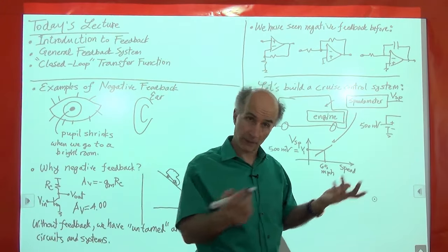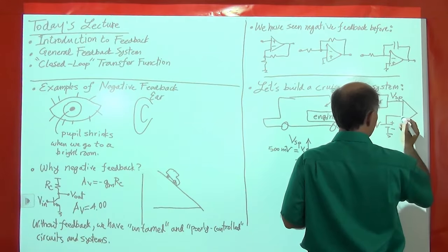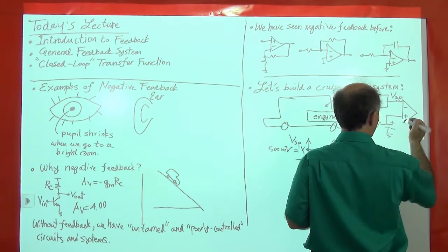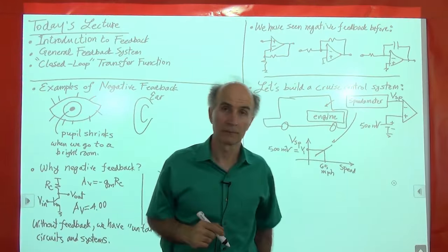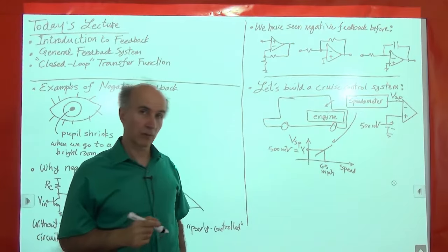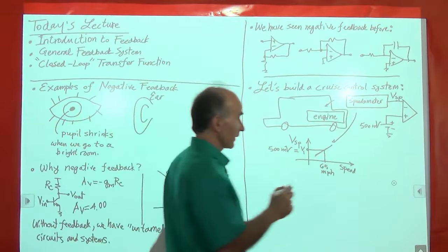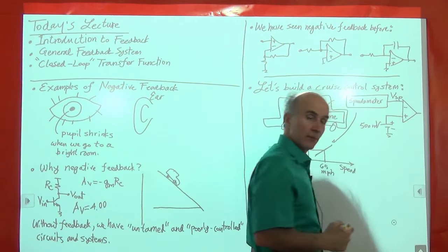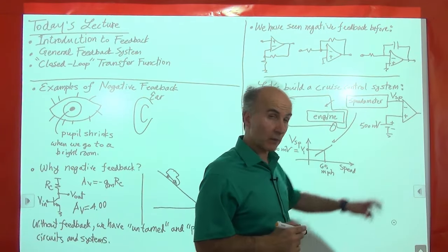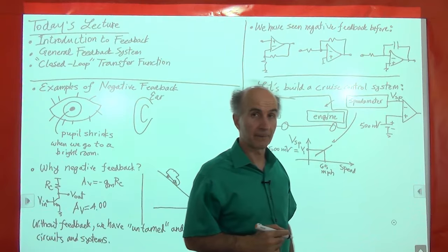I have op amps. Op amps can do that, right? So I'll take an op amp and hook it up like this, and I place a negative sign here, positive sign here. So far, so good? What I managed to do at the output of the op amp is generate a voltage quantity that is proportional to the difference between these two with a negative sign.